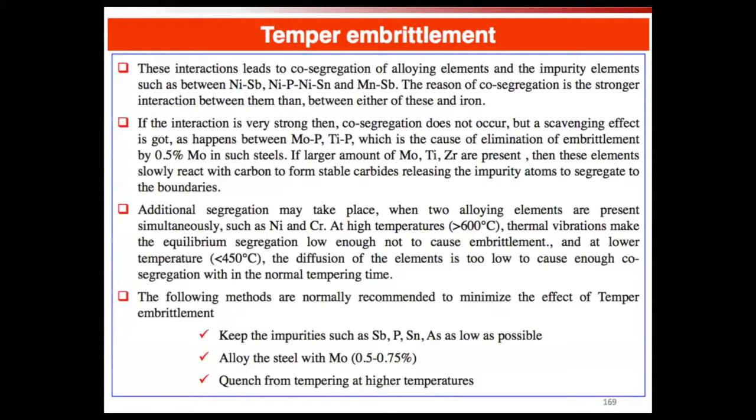That would slow it down, but it should happen at a rate that's irrespective of the amount of molybdenum that you have. It should happen whether you have the exact right amount, slightly less, or way too much. And carbon can replace the impurity. And diffused carbon is going to be first anyway, right? The first carbon will get in there, so the segregation will not have enough time to get in there. So it's going to form carbides anyway, right?